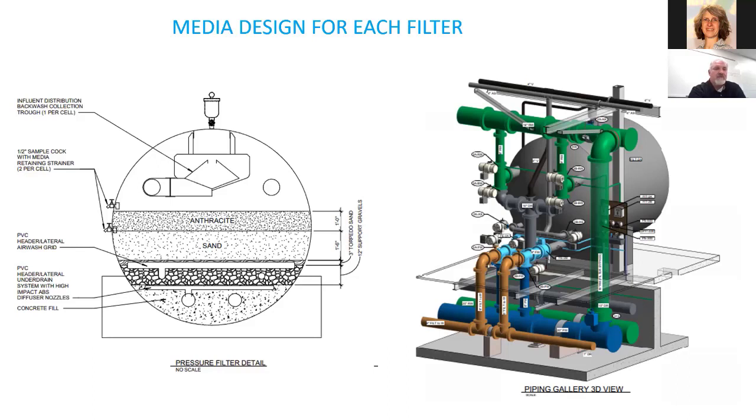The water quality tests that we currently do are iron, calcium, manganese, pH, chlorine free and total, fluoride, sulfate, and chloride.